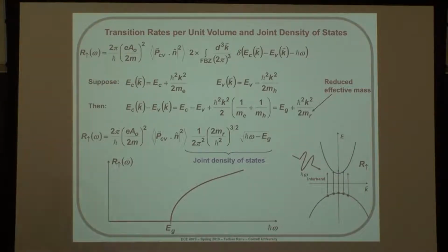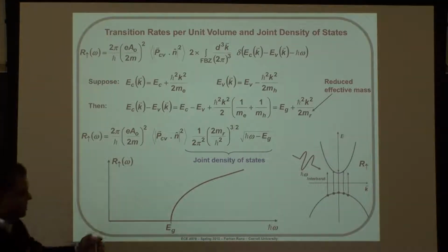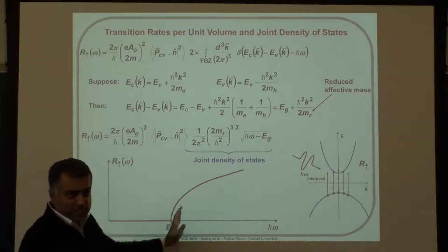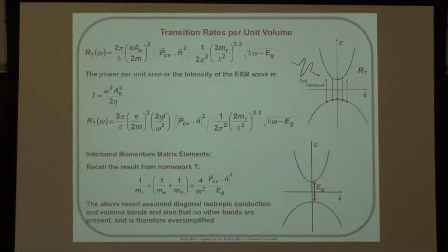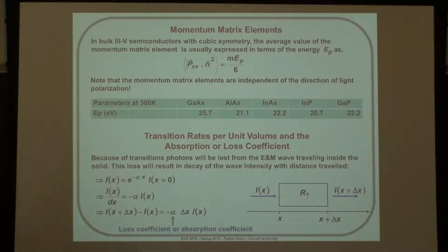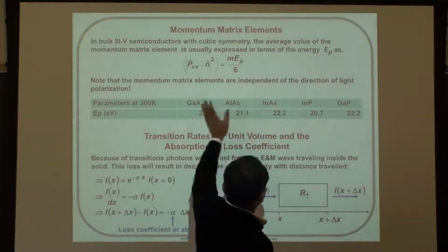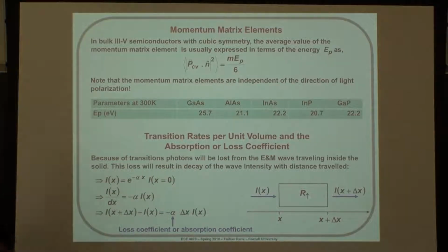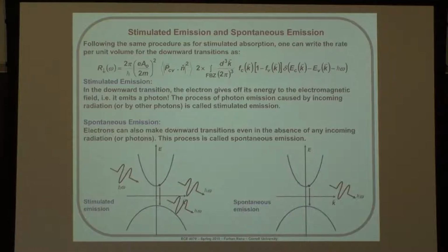So most of the lasers that are used today to power communication, to send signals into optical fibers, are not bulk; they are quantum well based. So they have a staircase sort of joint density of states, and let me just skip through a couple of them. For 1.55 micron, which is the wavelength used for optical communications, typically it's a combination of indium, gallium arsenide, and that sort of thing. You choose the right band gap based on quantum well thicknesses and all that. And there are some details here. Let me go to the point I wanted to make.